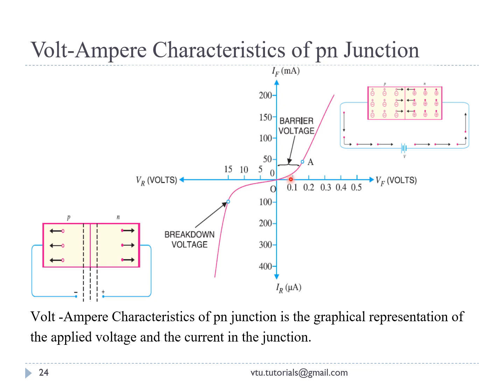When the forward biased voltage is Vf and the current due to the forward biasing is If. With the forward bias to the PN junction, that is the P type connected to the positive terminal and the N type connected to the negative terminal, the potential barrier at this time is going to be reduced.